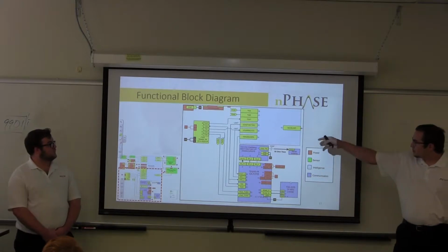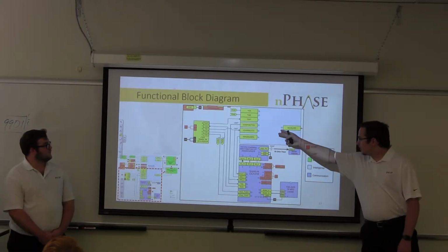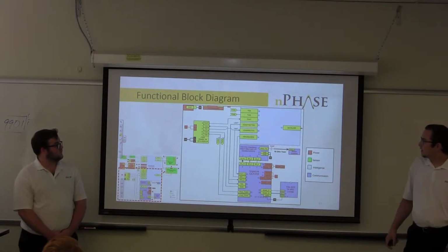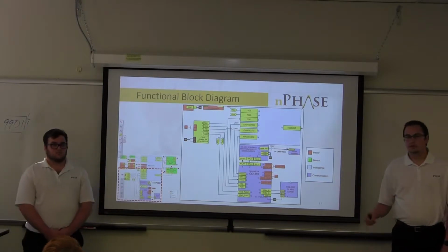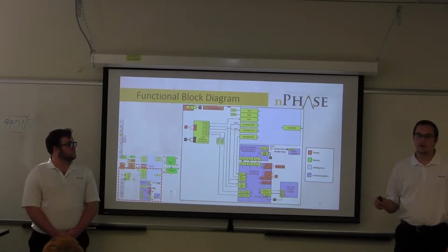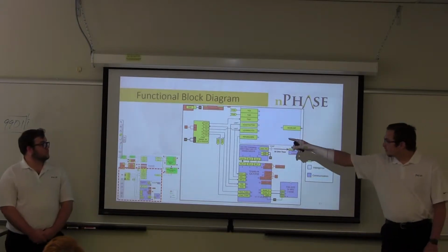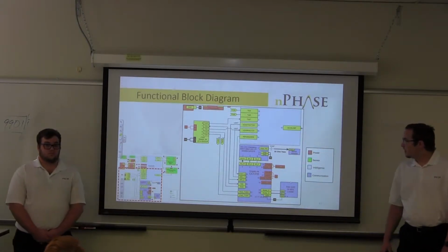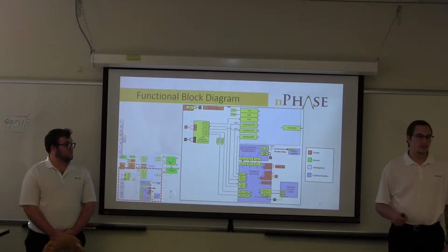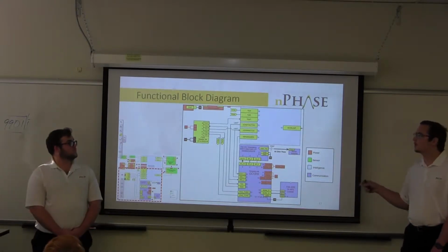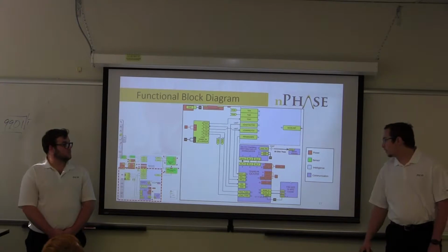And as you can see up top here, these 2 pins for TDO and TDI on the MSP430 share functionality with our UART protocol, and we can actually do both of those on the same pin by using the test pin on the top of the JTAG header. If we pull it high, we can program it using JTAG. If we pull it low, those pins will then be used for the UART protocol.